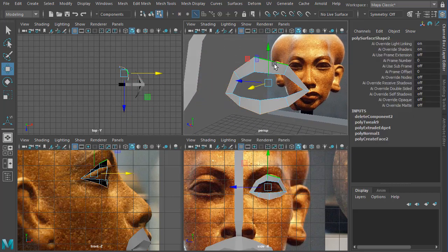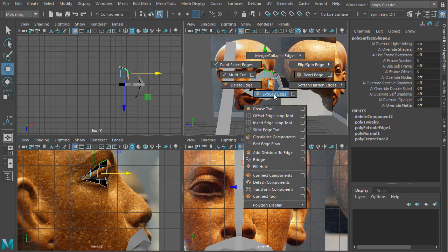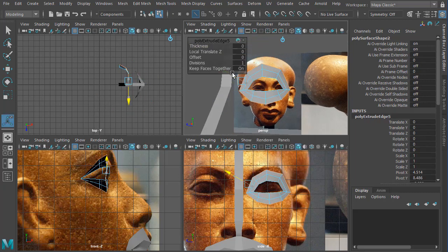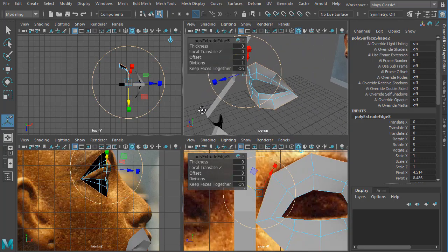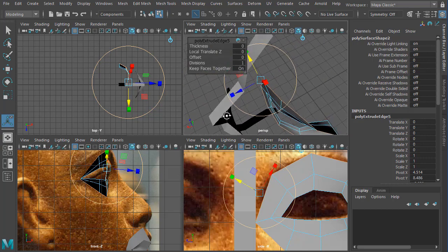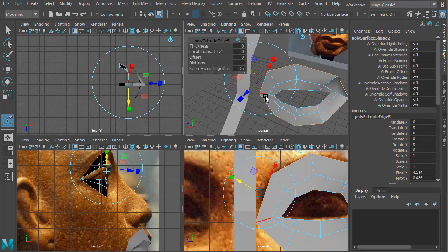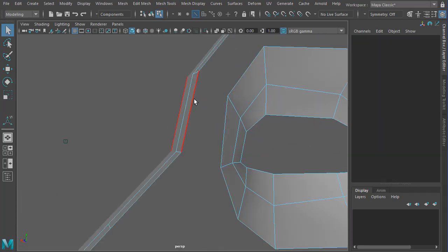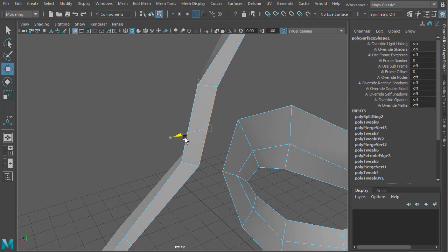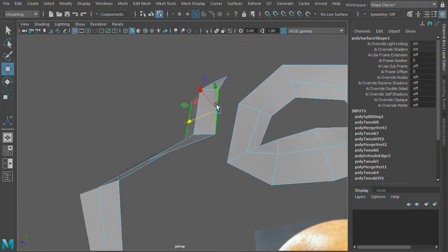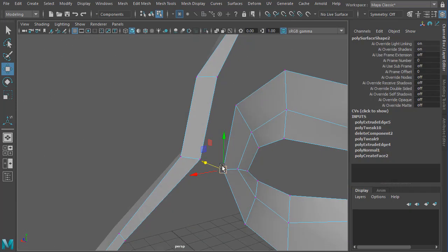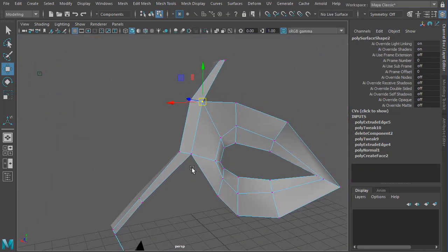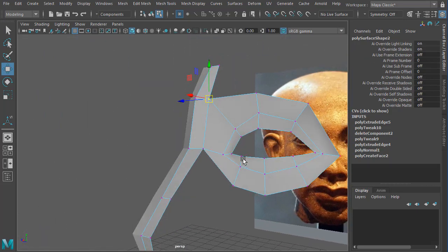Looking good. So once we have that, we can also do one more extrude, this time extrude edge, and it's gonna come out like so. So I think at this point it can start to touch here with the profile that we created. Or maybe I'll just draw one more. Let's see here. And I think I can just select this one and then push this a little bit backwards like so. And I'm thinking I can just connect this guy directly here. So I'll press V just to snap it, because it's two different pieces. We cannot connect them together. Okay, I think that looks good.